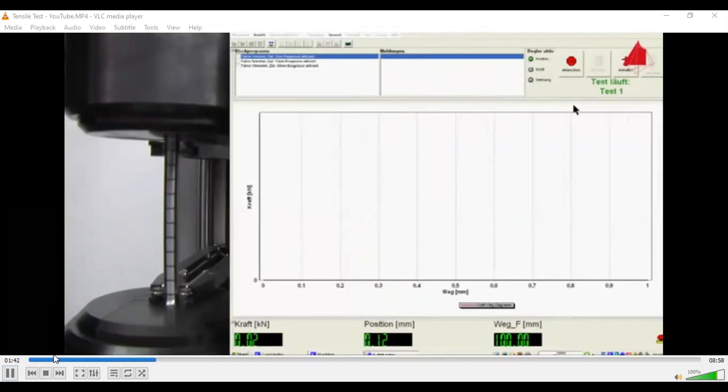The force. So what they will do, they will try to pull it from both sides and see at what point, at what force this pipe deforms or changes its shape or becomes thinner at certain points. The force that the test piece opposes to the imposed elongation is recorded and can be seen at the bottom left-hand corner of the computer display.